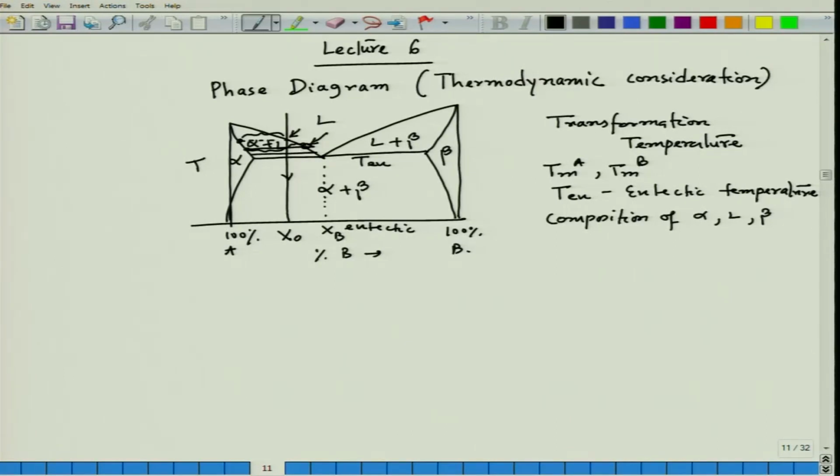So, like that way we will reach that point of eutectic temperature where the remaining liquid, this much liquid, will convert into alpha and beta as per the eutectic reaction, liquid converting to alpha plus beta, and this much amount would be alpha, and that alpha would have a name called pro-eutectic alpha. So, this amount would be alpha pro-eutectic, and this much liquid will get to this particular transformation.